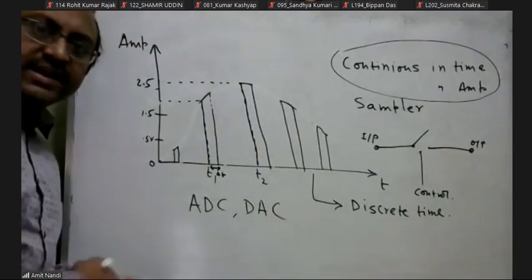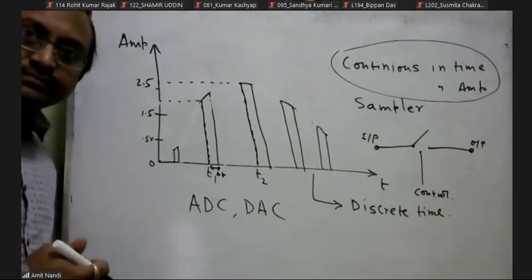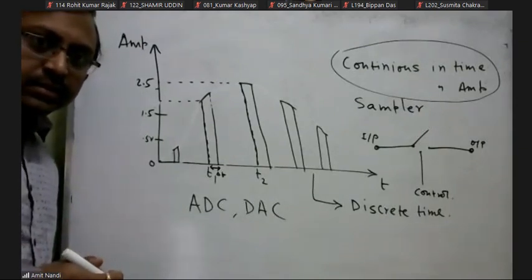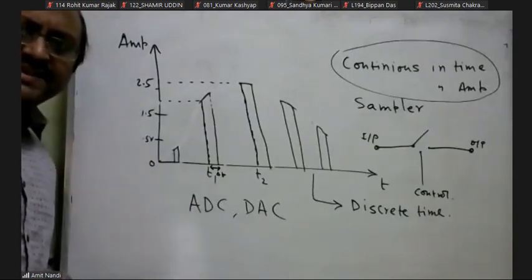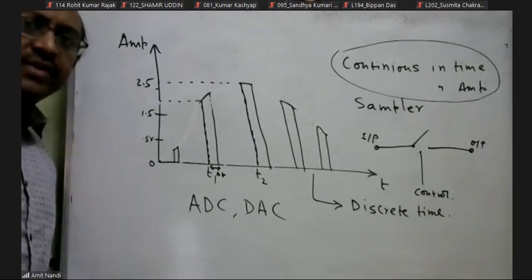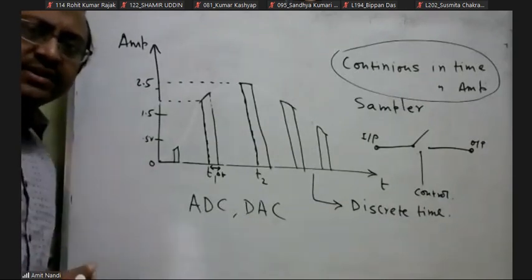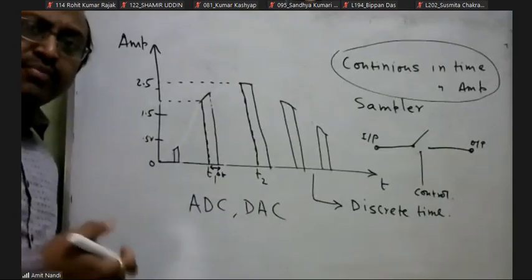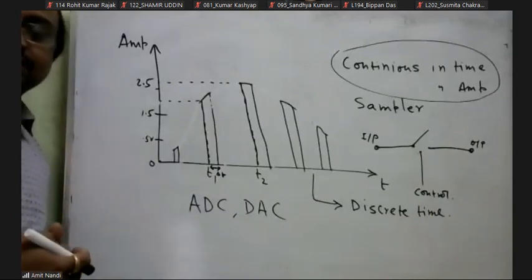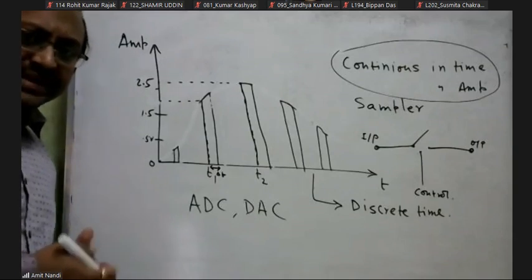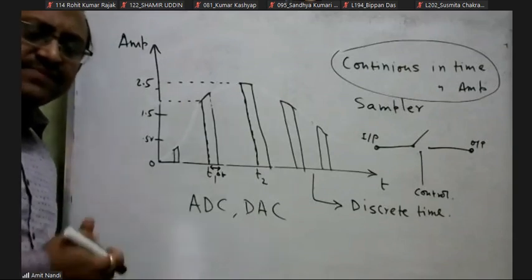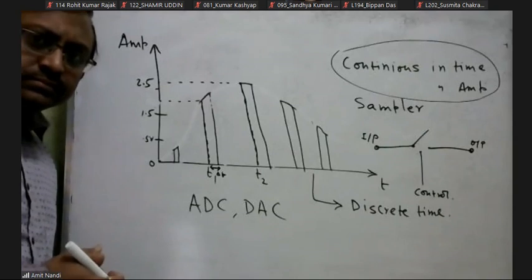Are you familiar with the ADC and DAC circuits? Yes, sir. Tell one example of an ADC circuit. Flash converter, flash ADC. In a flash converter, what type of electronic component is used as the basic component to build it? Sir, comparators.